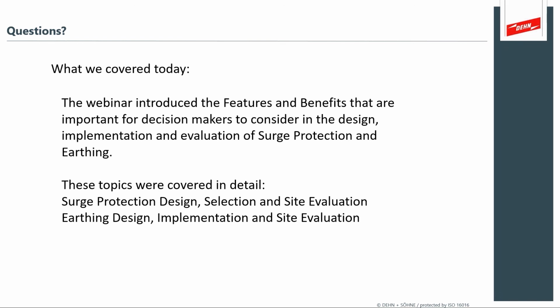Basically, the DEHN products are designed to release themselves after they've experienced failure, so that they don't sit on the AC power. So after a heavy lightning event, you will want to evaluate your SPDs. In normal maintenance cycles, it's probably once a year is sufficient to go through and look at your SPDs.